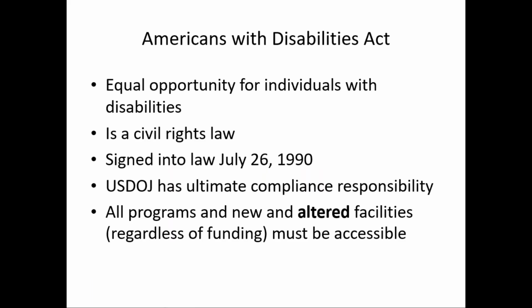And notice I've highlighted the word altered, because I would argue that when there's a sidewalk work zone, for whatever purpose, it might even be for building maintenance or for landscaping, but if it affects the movement of pedestrians on that sidewalk, we've altered that facility, excuse me, temporarily. But notice the requirement is that that altered facility must be accessible until the permanent facility is restored to use.